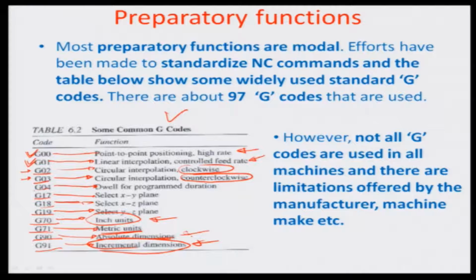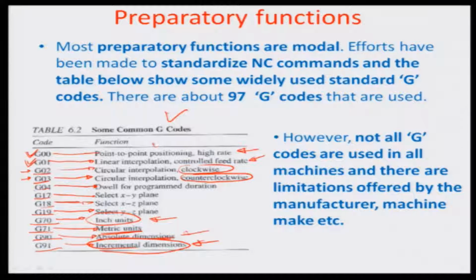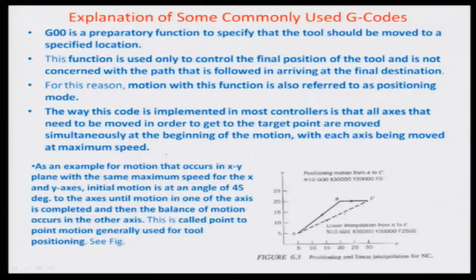So, that is what the preparatory functions are. We will now try to answer the question that I left earlier about linear interpolation as opposed to rapid point to point positioning, or rapid positioning. So, let us now look at the difference between G00 and G01.